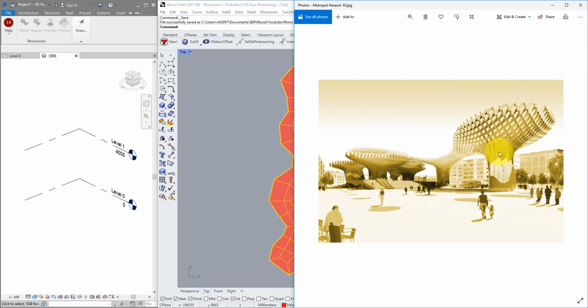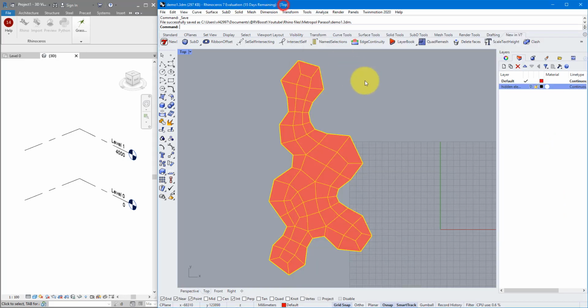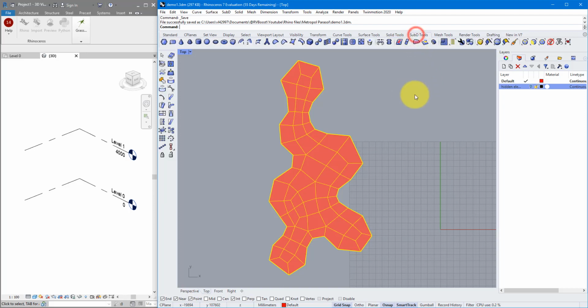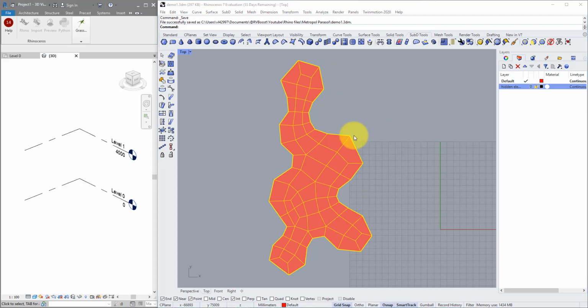we're trying to recreate. But don't worry, this is all part of the plan. Because in Rhino 7 here, we can certainly make use of the new feature called SubD modeling. This is a group of commands that are now under this new tab, SubD Tools. Essentially, this is the method of modeling where we define our form in a skeleton or ridge-like manner, as I have done with this mesh surface here. And then the SubD engine will automatically smoothen our mesh to create the freeform object for us. We are using this approach because it offers an easy way to merge different surfaces into a single form.